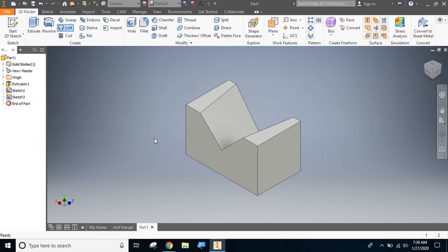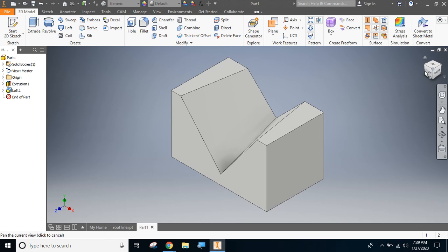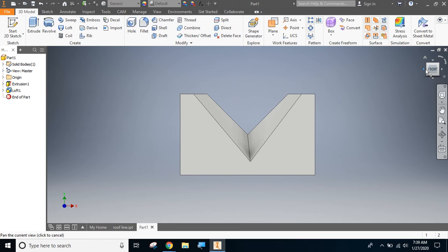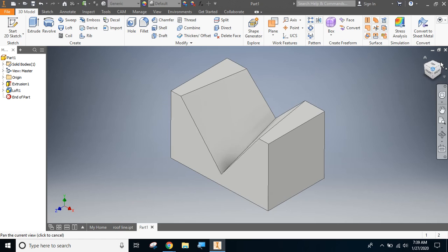I like what I'm seeing, so I'll click OK. And there I've got that lofted shape drawn through there where I've got a little different profile from each side. So we can only do shapes like this where the extrusion, or the cutaway, if you will, flares in or out using that loft tool.